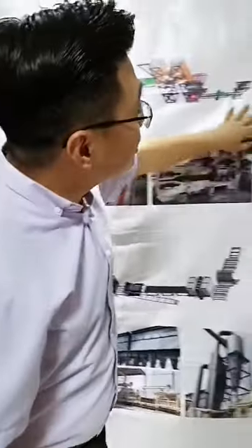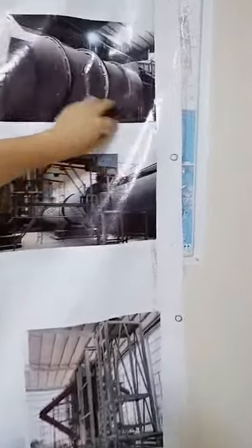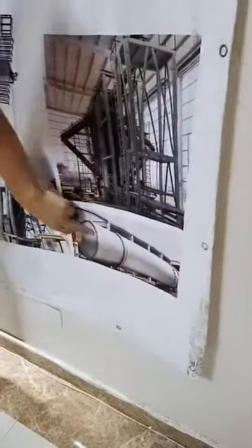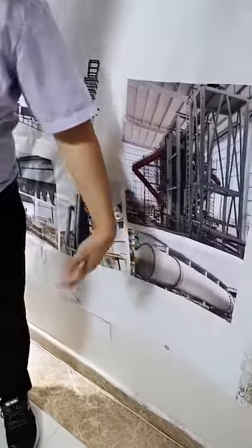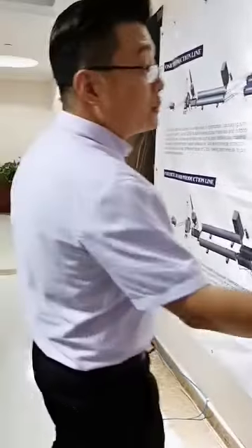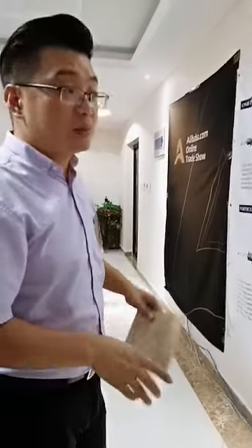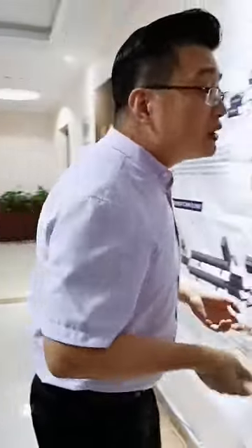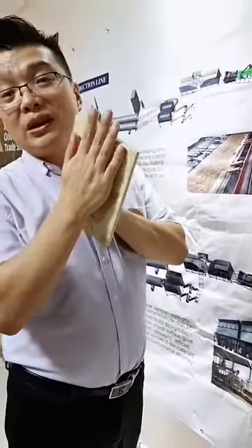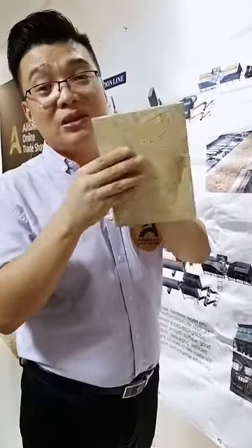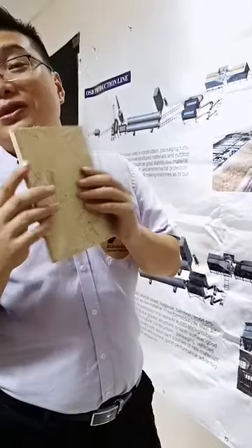Now you can see this dryer is for the OSB, and this dryer is for the Particleboard, so you can see the difference. But the hot press is actually the same, and the trimming saw is the same. Another difference: for the OSB, there is not much sanding. Some factories even don't have a sanding machine. But for Particleboard, they always have a sanding process.